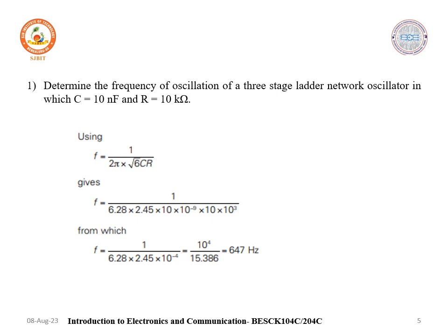The crystal has high impedance at the parallel resonant frequency, where R, L, C and CM determine the resonant frequency. The crystal has high impedance at which 2 pi FL is not equal to 1 by 2 pi FC. The series and parallel resonant frequencies are very close. We can consider this: the crystal oscillator gives a constant frequency based on which crystal we are going to use.